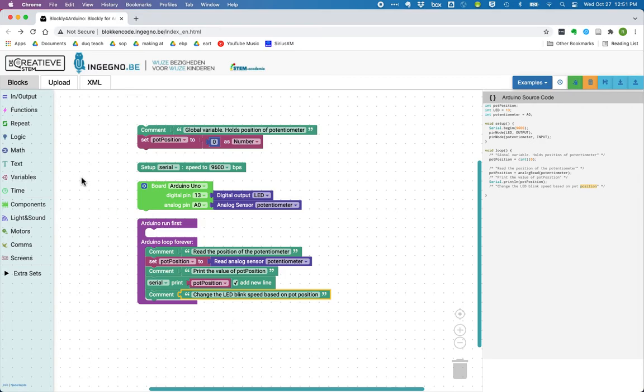And the way we did it was we set the pin controlling that LED high, waited for, in the case of last circuit, 2 seconds, turned it low, and then waited again. We're going to do the same kind of thing.